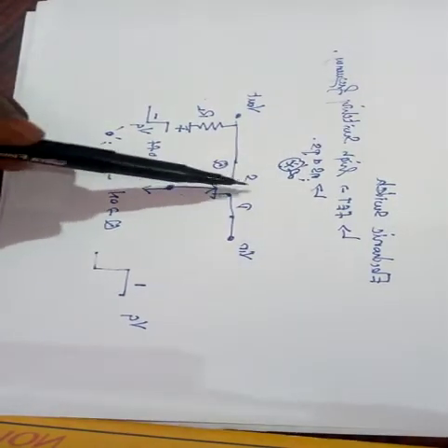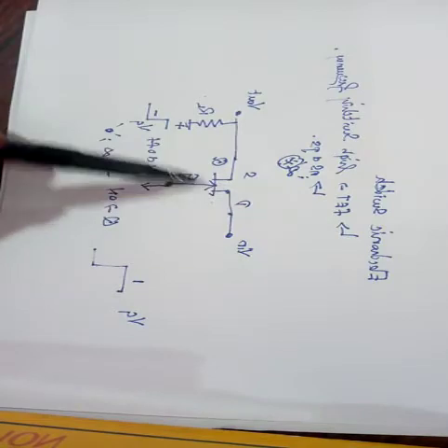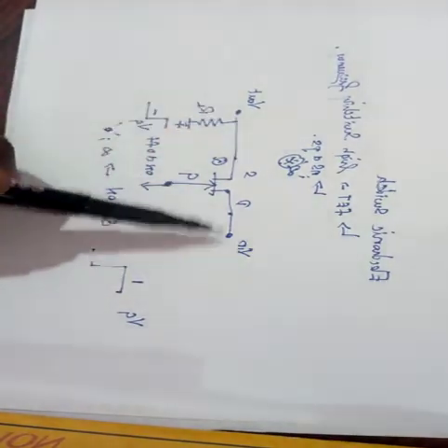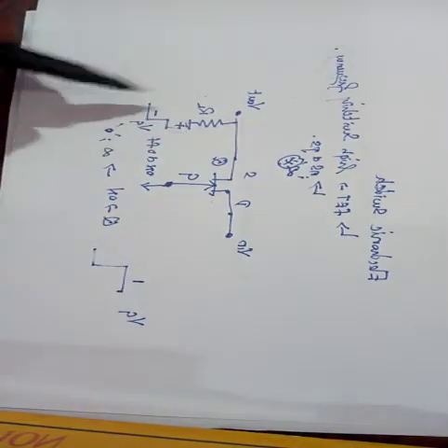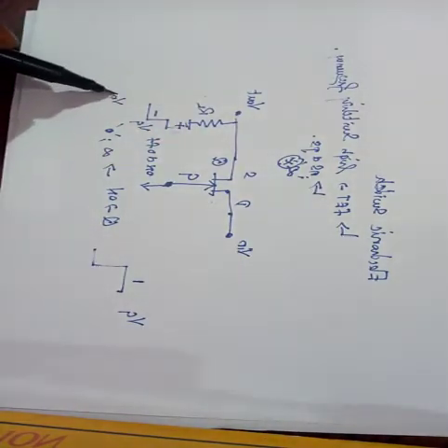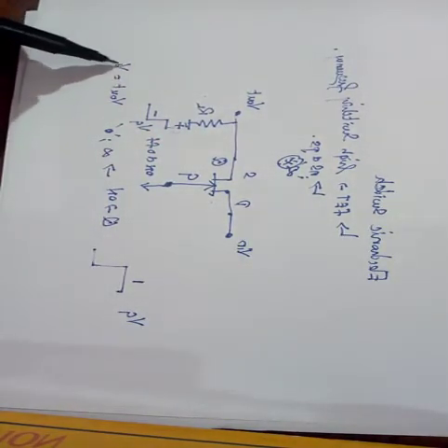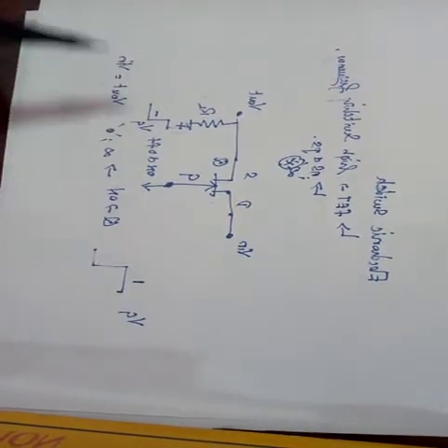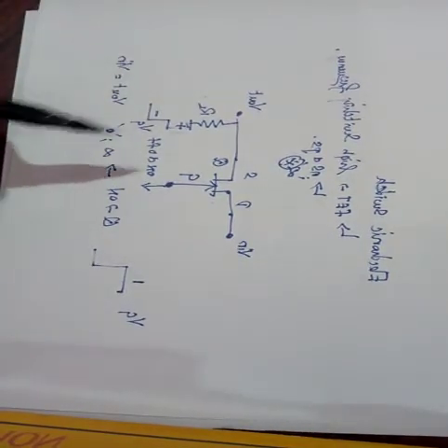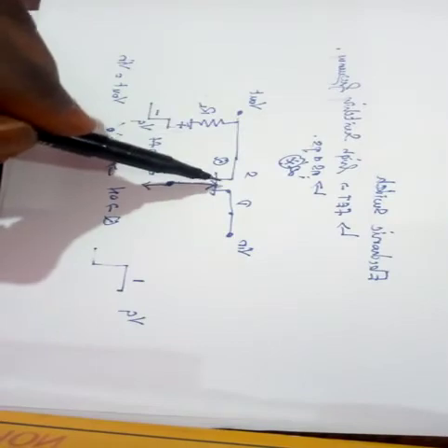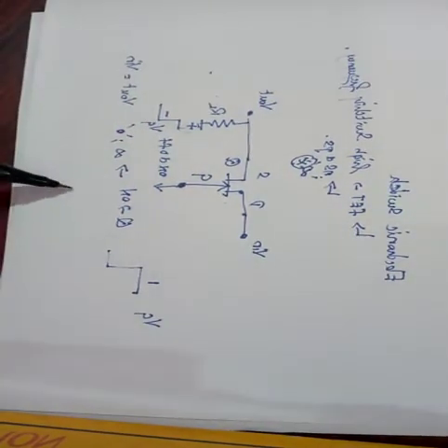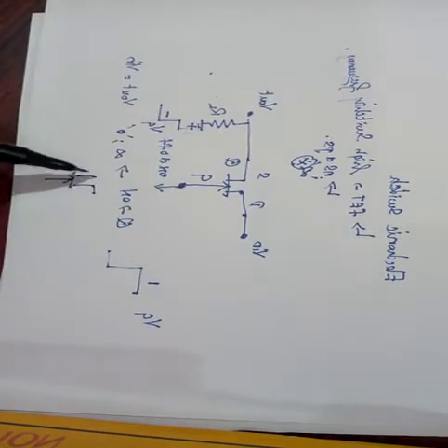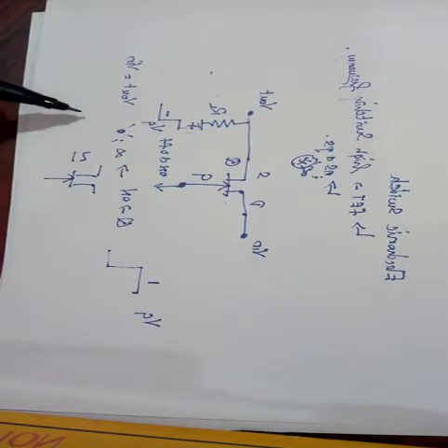So no signal will be dropped across this zero resistance transistor, and the input will be present across the load. So the output V out will ultimately be V in. Let me explain it as a truth table. Equivalently, let me draw this as a switch like this. This is my gate, this is my transistor, so I'll equivalently draw it as a switch.